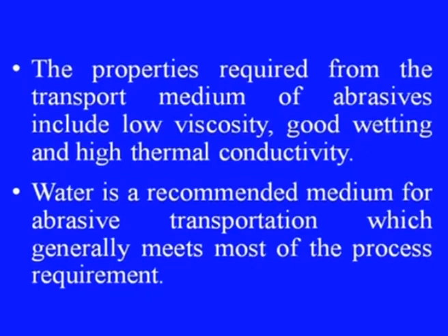The slurry is pumped across the tool face. The slurry pump is a part of the machine system, as we have seen already. The properties required from the transport medium of abrasives include low viscosity, good wetting, and high thermal conductivity.